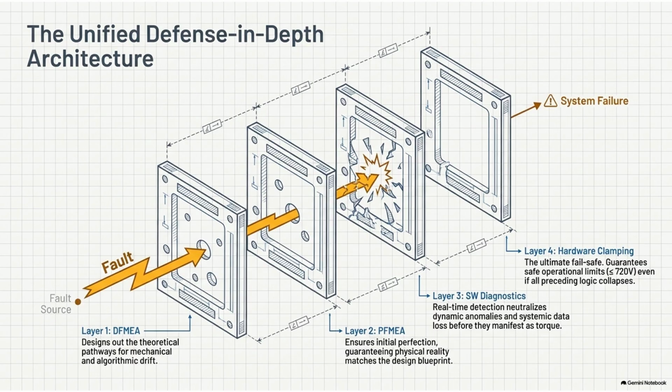So after baking for 30 minutes at 18,000 RPM, they hit the motor with 100 extreme acceleration and deceleration impacts. The engineering specification demands an angular acceleration of 25,000 radians per second squared. Let's pause on that number because 25,000 radians per second squared is really hard to visualize. For the non-physicists listening, that is an incredibly violent physical shock. That is the equivalent of a heavy mass spinning at top speed and essentially slamming a solid steel bar into the gears to stop it, reversing it, and slamming it again over and over and over.